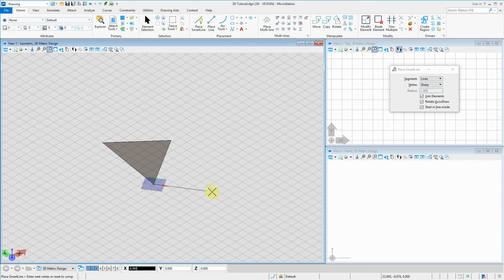You can see how it gets highlighted. That means that it's locked in this direction. You can also lock the direction by just pressing enter. And then we can place a distance of, let's say, 5, and so on and so forth. And then we can draw like this. And we can even reference that if we lock the direction, press enter, we can reference that it's going here. So this is essentially your way of creating and drawing in a 3-dimensional environment.